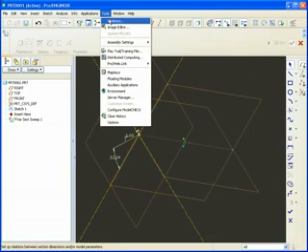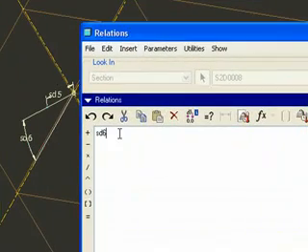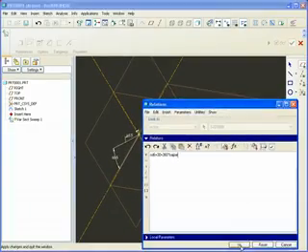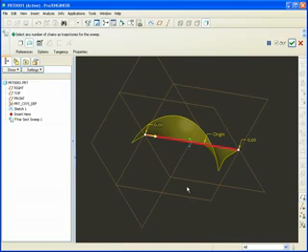If I go to Tools, Relations, I can pick that angle, give it a relation that essentially gives it some instructions on how to change. So we'll say SD6 is now equal to perhaps 30, which is about what it is now, plus 360, but I don't want that 360 to be added immediately. That's where I'll use a quantity called trajpar, the trajectory parameter that returns a value of 0 to 1 in length of the sweep. Now you'll notice that we have a bit of a corkscrew going on.